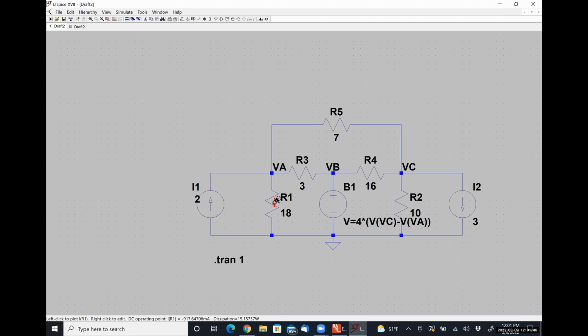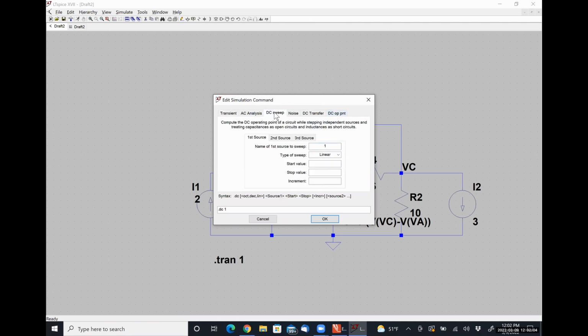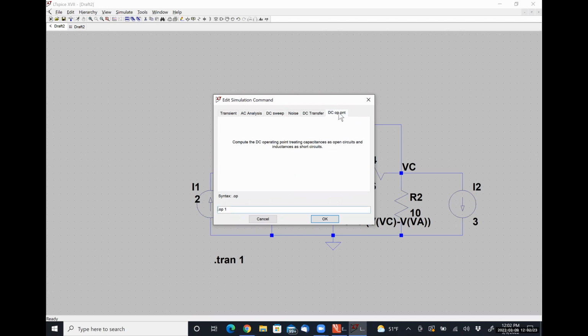I didn't quite hear you when you said, so you simulate and then run and then DC sweep. No. Okay, so for this particular circuit, our first analysis was a DC operating point analysis. With DC sweep, effectively what we can do is sweep our sources to make them have different values and then see how things change. Since we had a DC circuit where literally nothing was intending to change, we did a DC operating point analysis.